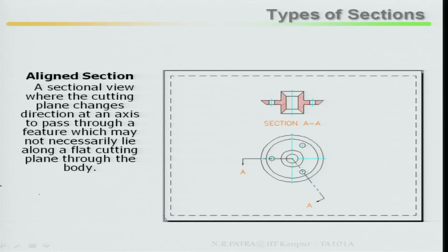Then aligned sections. If there are cases where your holes are not symmetric and at the same time maybe the holes are different holes, then you can put an aligned section so that you can show features inside this hole.